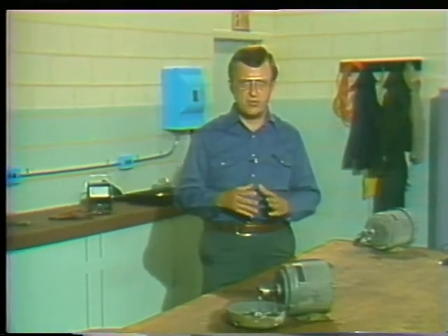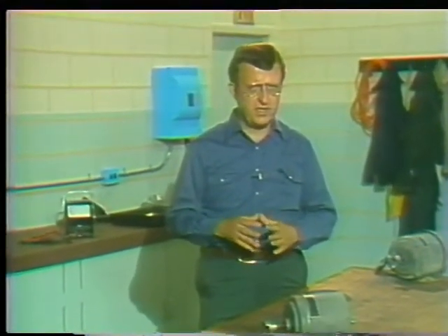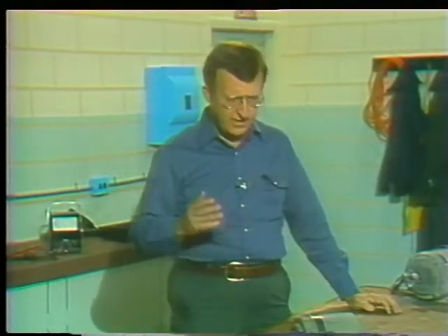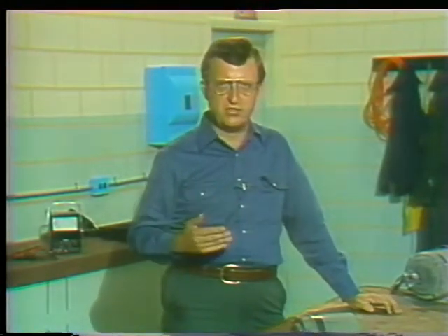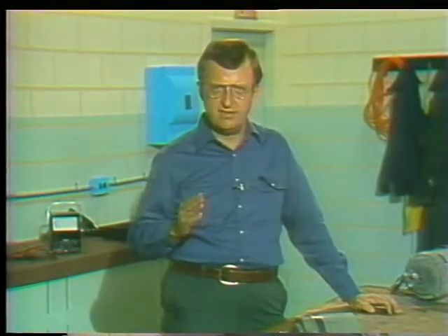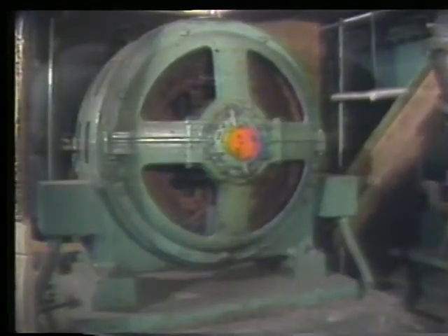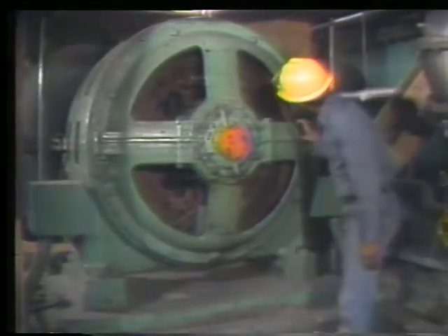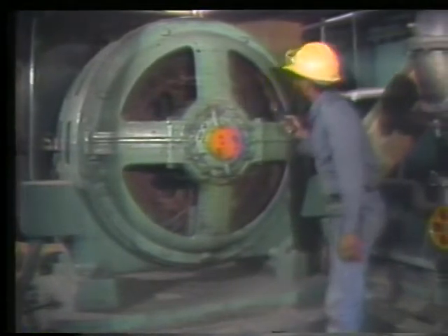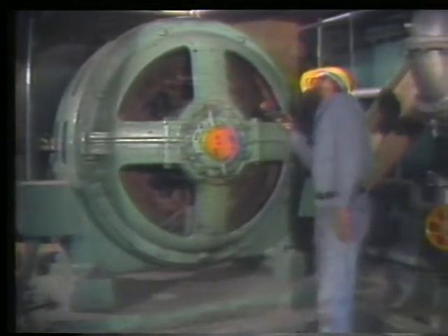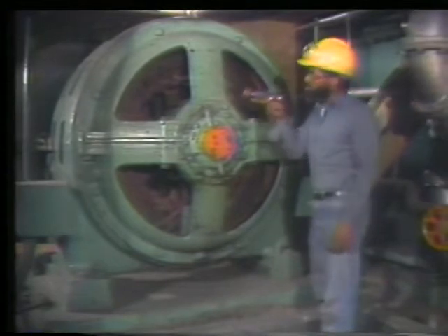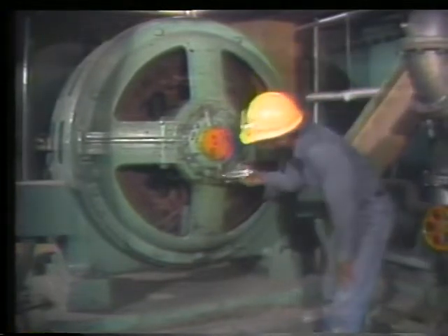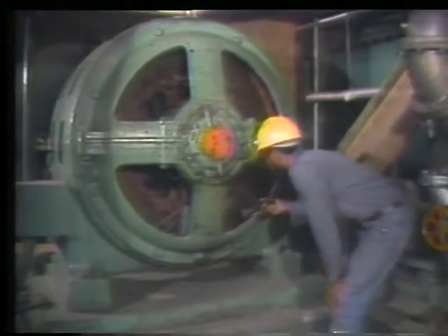To ensure a motor won't be started while you're inspecting it, tag the motor out or have it tagged out according to your plant's procedures. Then, begin your inspection by, once again, using your sight. Through the ventilation slots at the end of the motor, you can usually see the stator windings. Look for discoloration of the motor's insulation, signs of burnt insulation, and dirt.